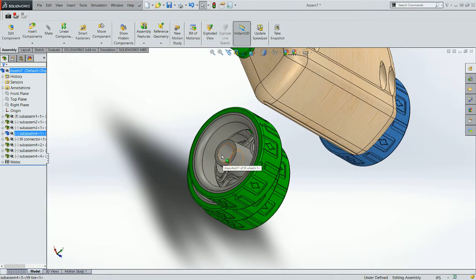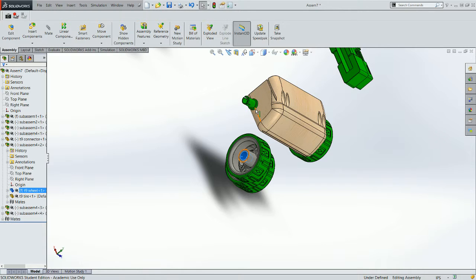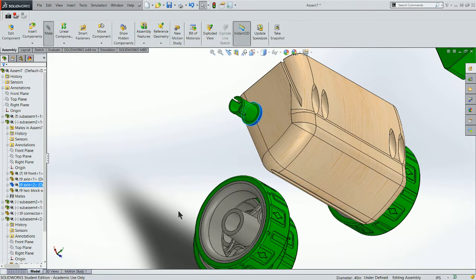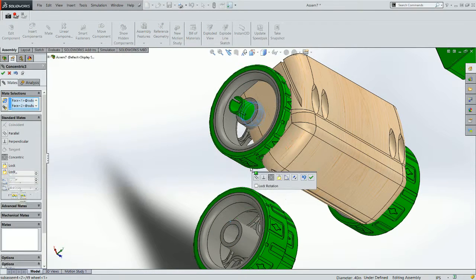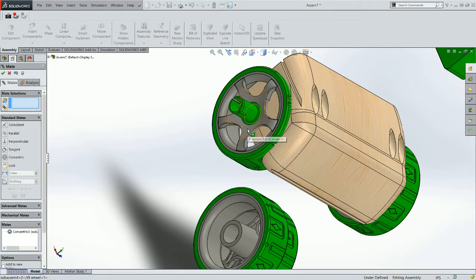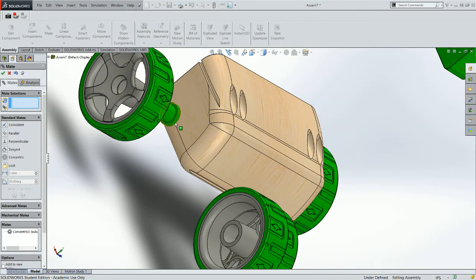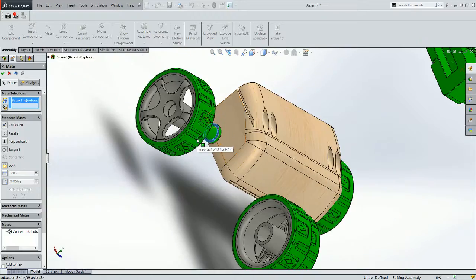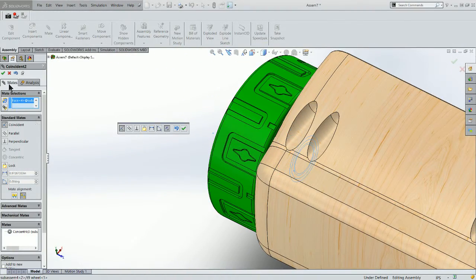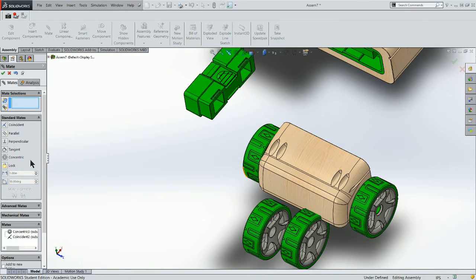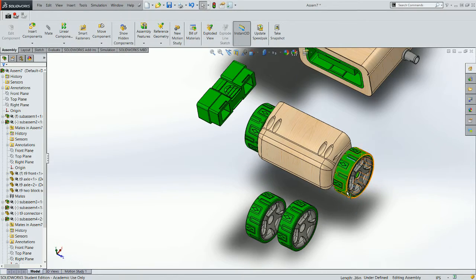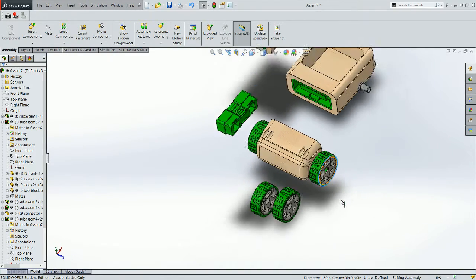So let's go ahead and finish mating these about my axle shafts. Flip that orientation. Accept it. Line up the wheel hub face with the rim face and accept that. Now you'll notice that I don't have these wheels. They will still rotate here. Well, you'll see that here in a second.